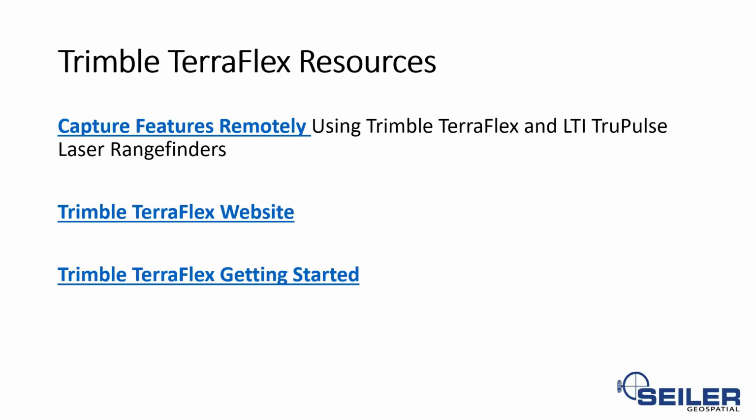Good question. Okay, so there's a question out here: how would you account for laser height in TerraSync to obtain accurate elevations for features? It depends on what type of laser rangefinder and what kind of device you're using. If you are using a Geo7X and have a built-in laser rangefinder, you would go into the rangefinder app and set your elevation in there, also needing to run a monopole. So there's a bunch of other questions that need to be asked before we can determine if you can accurately take elevations inside of TerraSync.